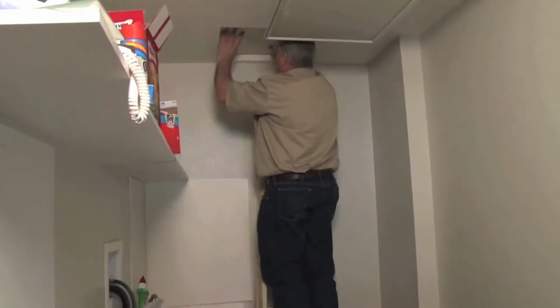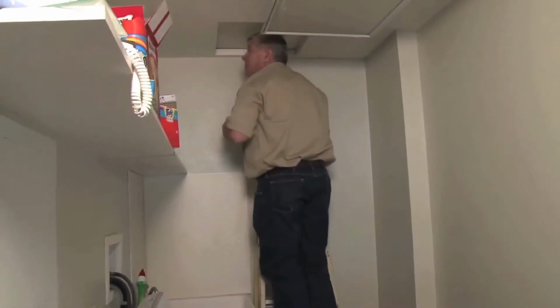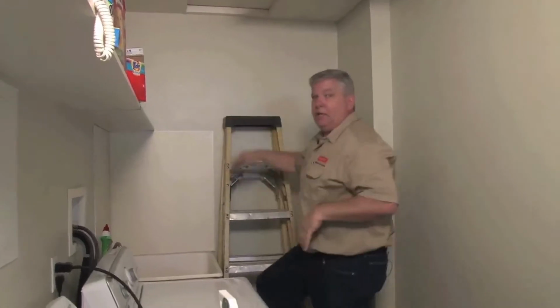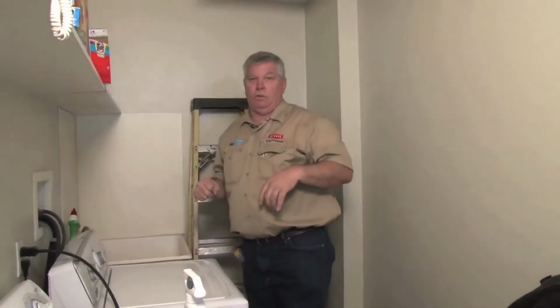After evaluating the attic, we find that the insulation is adequate. It could use a little bit more. The ducting appears to be in good shape, and the structure is strong enough to hold the unit on the roof. Now we need to go up on the roof and get the model and serial number off the existing unit so we can compare it and see what the load comes out to.